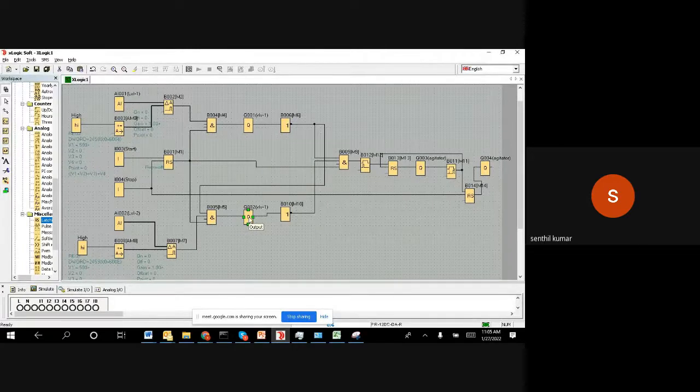So once your second valve is open, this tank level we are going to simulate. Once it becomes less than 500, this valve also will close. When this valve is closed, this will become off, and the output will go on. So in this AND gate, first one will be on, second one will be on, and the third leg, as long as you did not press the whole sequence stop, it will be on. Then when all three are on, we are making a small pulse and setting it to start the agitator.